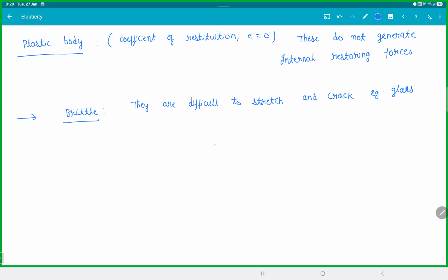So what actually happens when you have a bulb? Because of the heat, it gets really heated up. All you need to do is put a little water droplet here. So this part will cool down and try to contract, but this part which is heated will try to expand. The glass will break. Just put some water on a bulb. Switch on the bulb for 5 minutes. Once it gets hot, put water. The glass will break automatically. Bulb is gone. That's what actually happens in the movie.